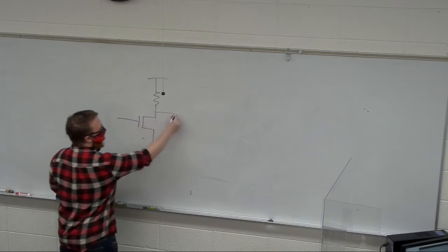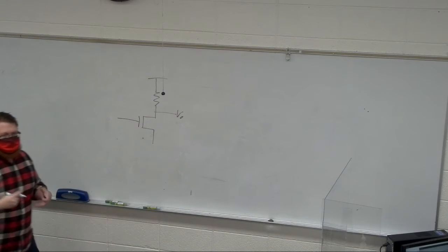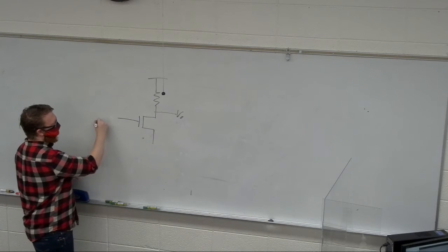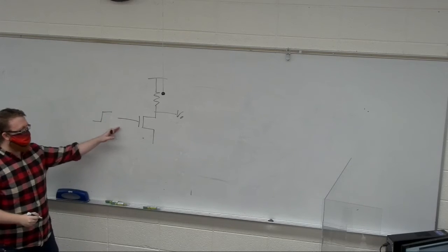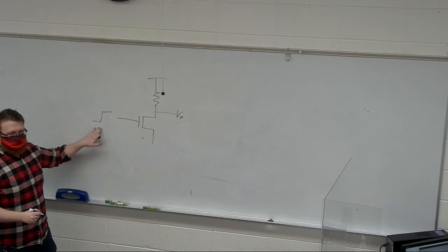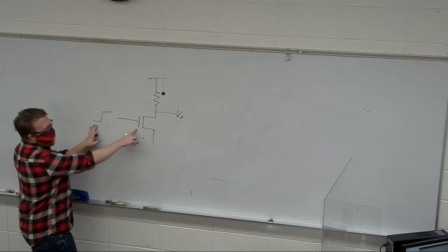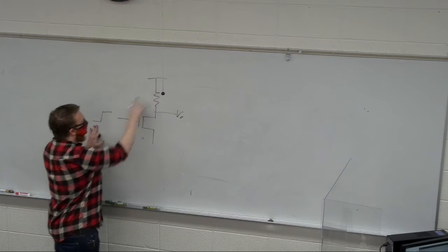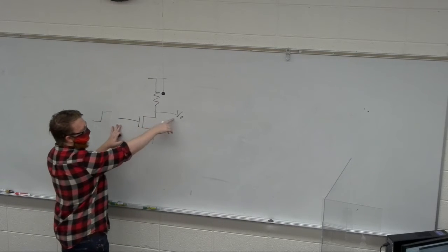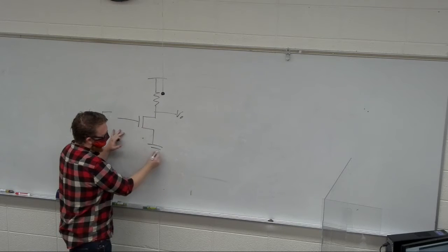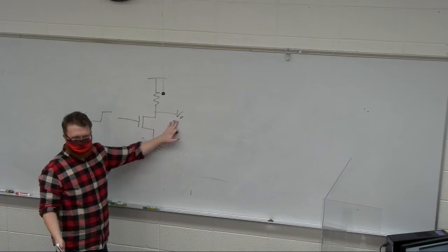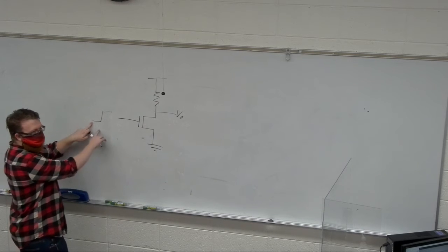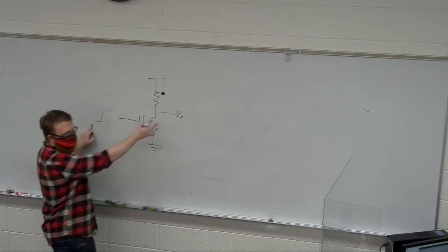So say we have this circuit, and this is V out. The two things that can happen is either I turn the circuit on, right? If I go from a 0 to a 1 here at the input, when it's a 0, that means this is off. V0 is pulled high through this resistor. When I turn this on, it shorts V0 to ground, and V out is 0, right? So it's inverting, right? 0 here means 1 here. This is just an inverter.